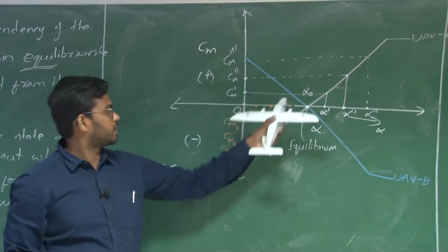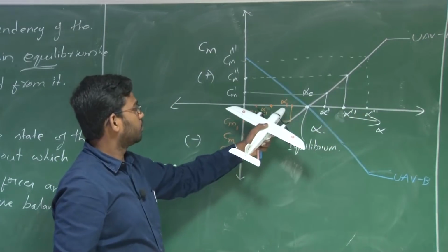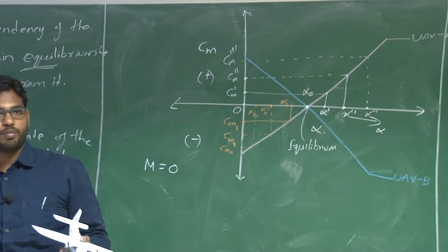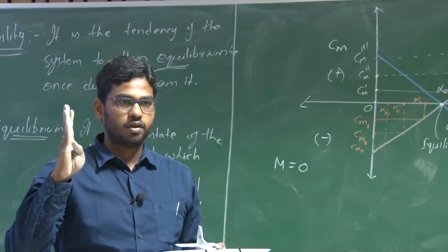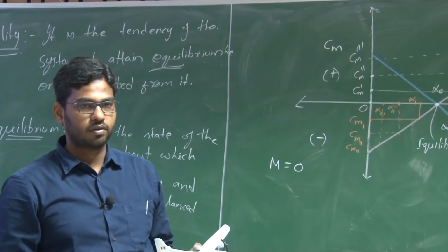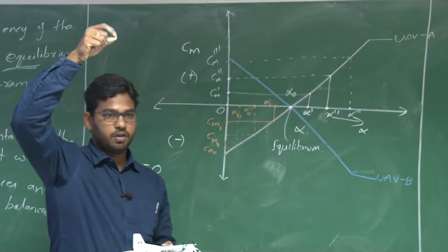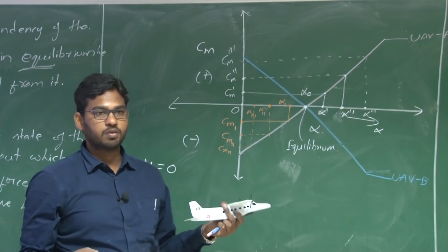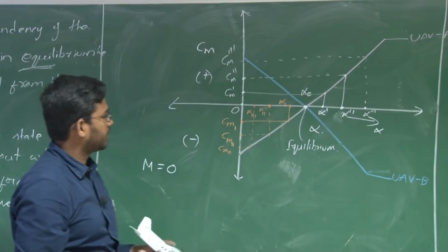So in either case, if you follow a UAV with this pink curve, you will end up moving away from the equilibrium once disturbed from it. Similar to a pendulum case, where you have an equilibrium, but it is at minus pi by 2, sorry, if the CG is about the pivot point, then the equilibrium is not stable, the system is not stable about that particular equilibrium, right.